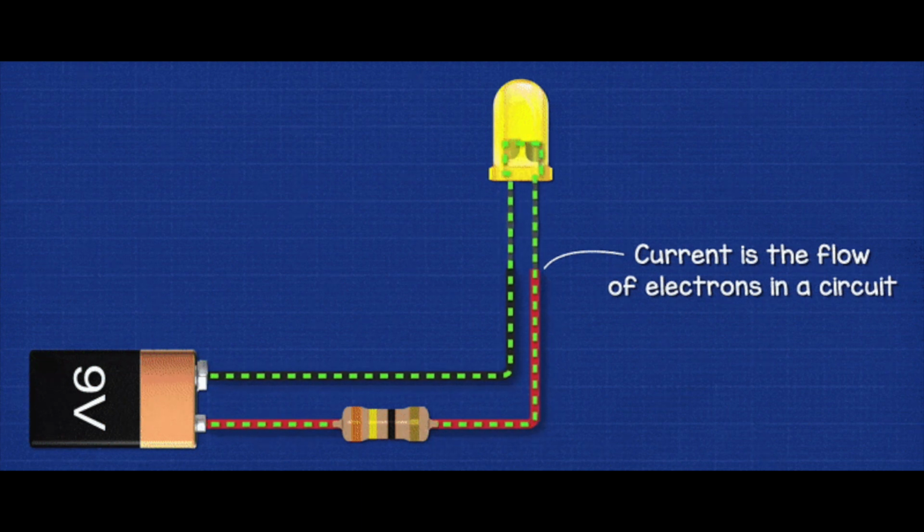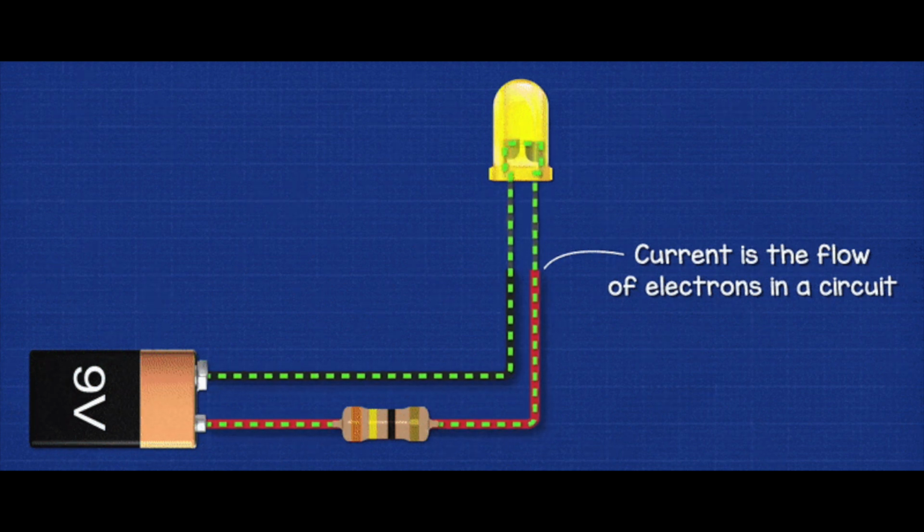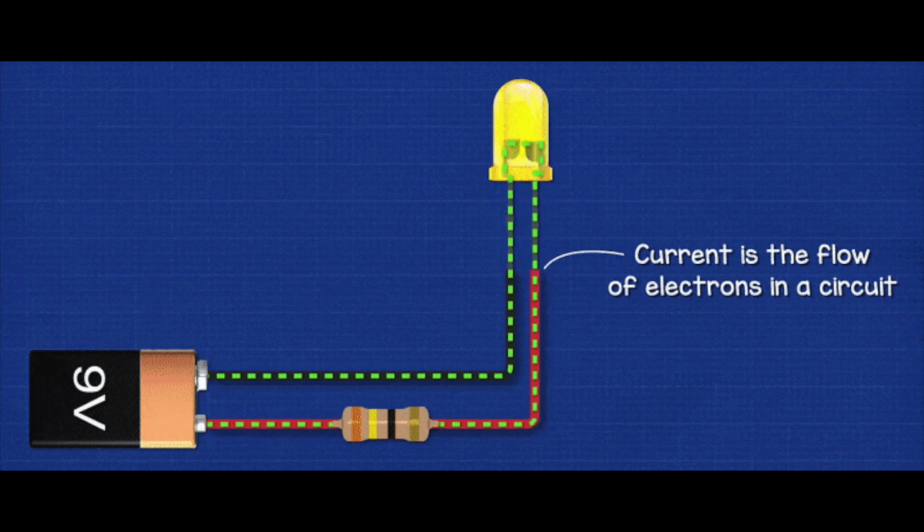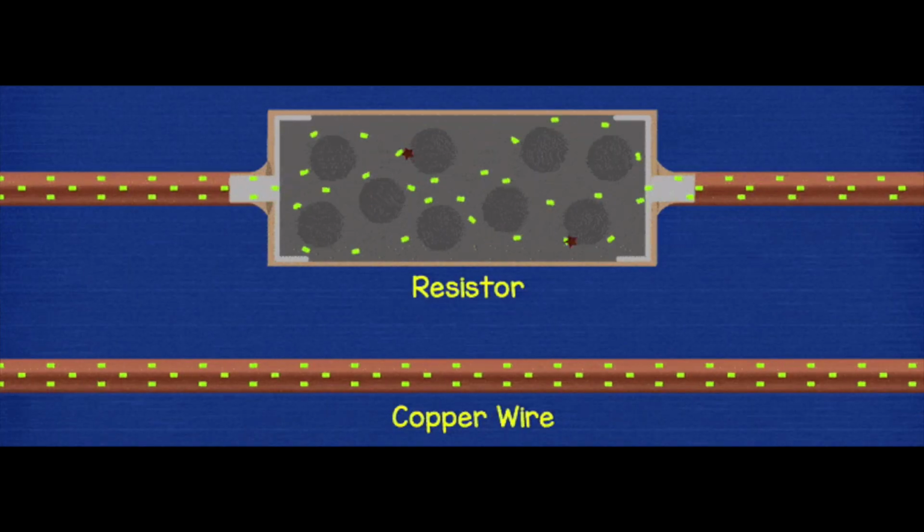Chemical reaction happening inside the cell gives a positive potential to one electrode and negative potential to another electrode. That is, there will be deficiency of electrons in one electrode and excess electrons in another electrode. As a result, electrons move through the conductor and reach the other terminal. The battery provides electrical energy to the electrons. The electrons move through the LED bulb and electrical energy will convert into light energy.